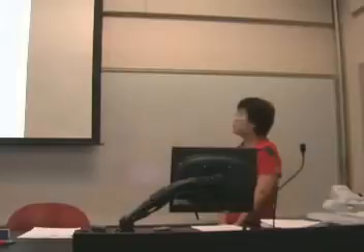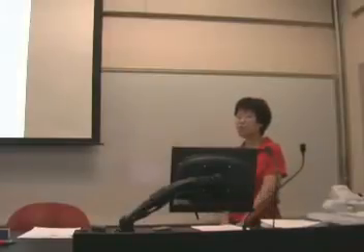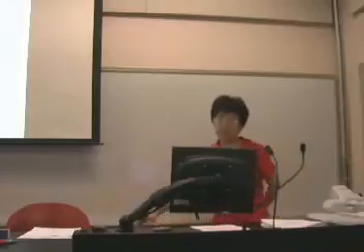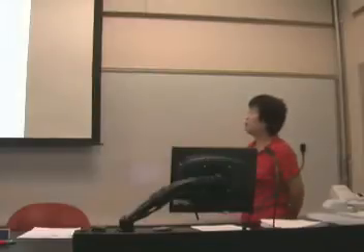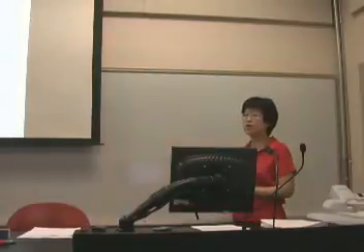As we said, in MATLAB there is the interp1 function, and it can perform different kinds of piecewise polynomial interpolation. This shows you how it works using different function options in MATLAB. The first one is linear, the second one is called nearest neighbor, the third one is called spline, and the last one is called pchip. Here is an example, and I'm going to walk through the example with you after we talk a little more about the last slides, and then we will go back.